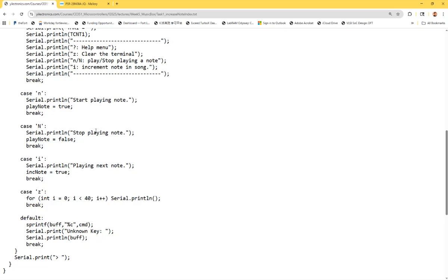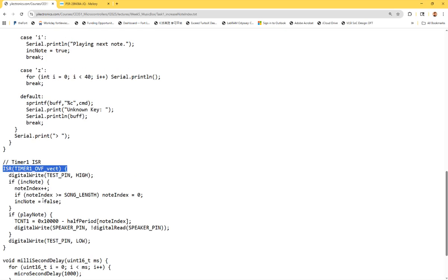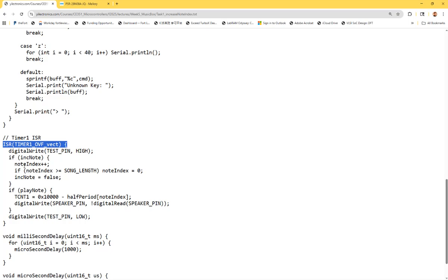If the flag is on, we do something, but we don't really jump into a function. If you jump into the function, it allows you to do a lot of other things, because you can put a lot of operations inside that function. So whenever overflow gets triggered, it gets into the ISR and does a lot of things for you. Okay, so that's the goal here. So what's the vector's name being used for the ISR? And the answer is just over there, right?